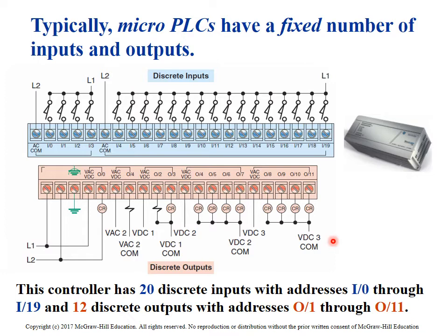The PLC can never be used as a safety device. So in order to create a safe environment for our operators and fellow employees, we have to control the signals going to those outputs using safety devices like safety relays, safety circuits, and gate circuits. When the operator is in a zone or area where motion takes place, everything ceases to move, and with this power disabled here, none of these outputs can turn on.